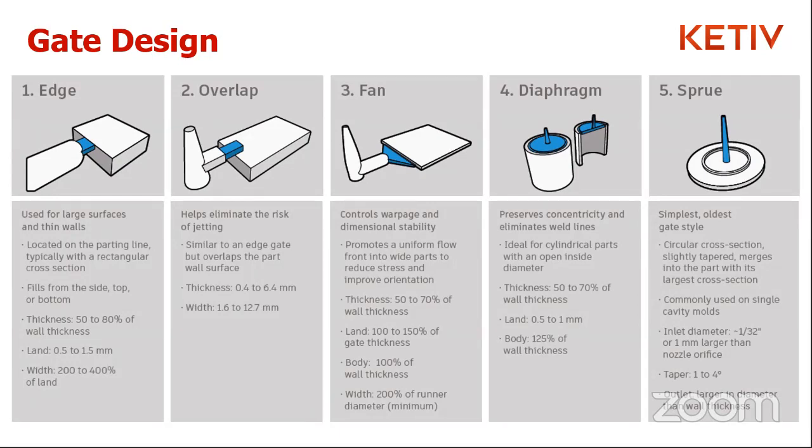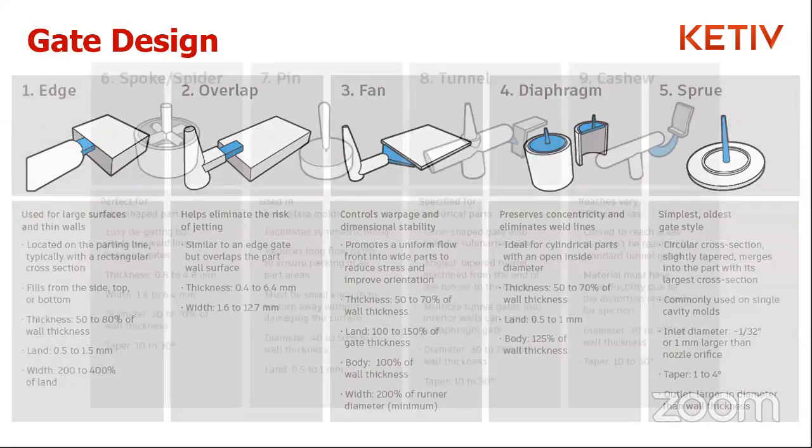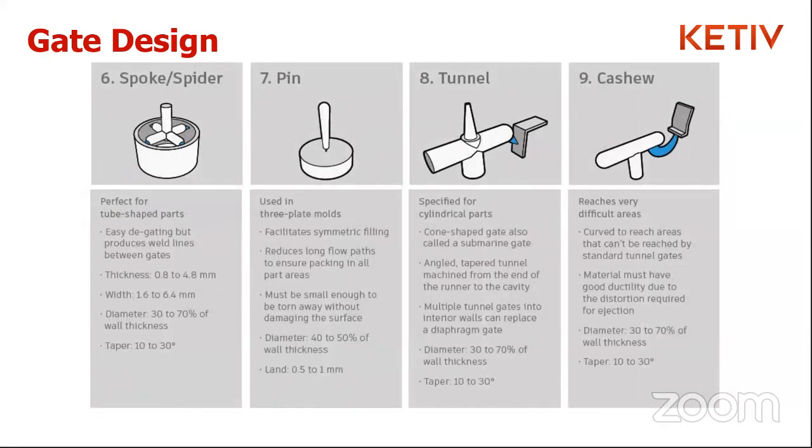And you might be missing a different cooling approach, a different gating approach that really gets back to what we need to explore for the part functionality, performance, quality criteria, as well as the individual ingredients going in. For example, material: is that material shear sensitive, or color combination sensitive to shear rate, shear stress?